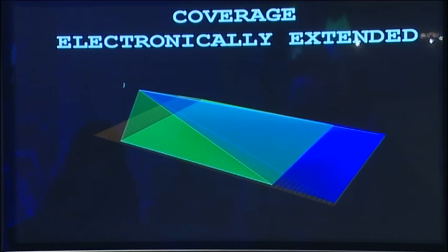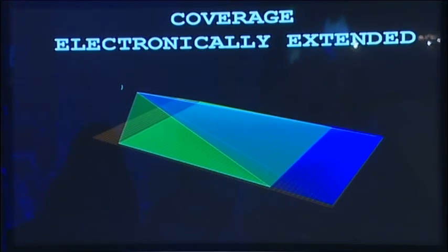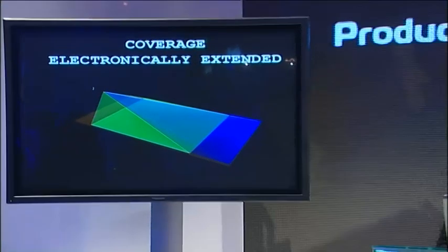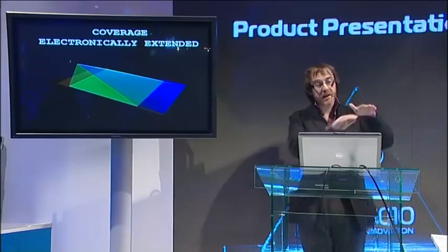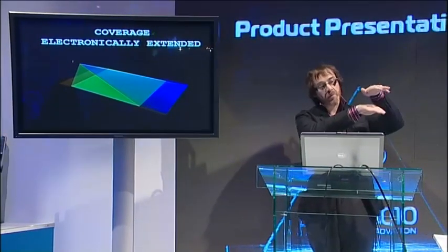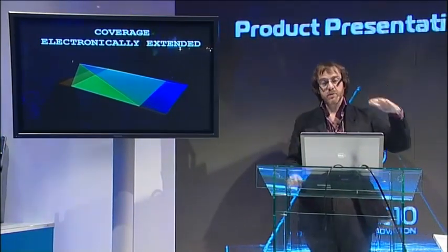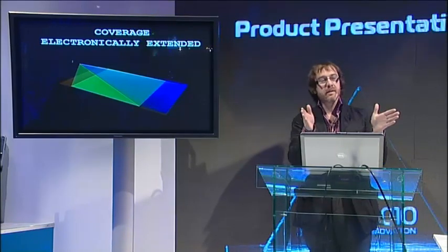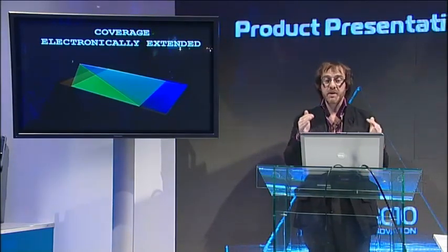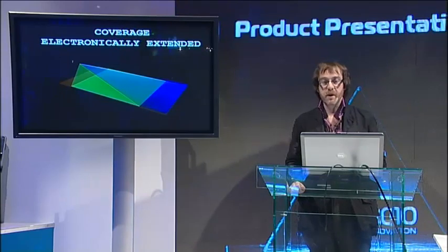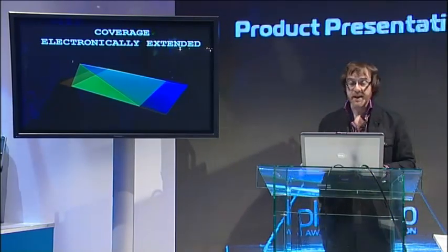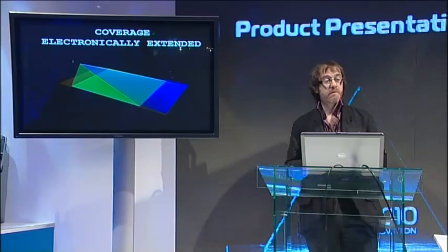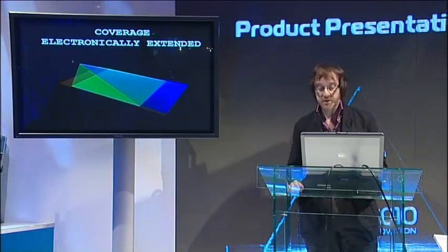You can also adjust coverage close to the stage as well as far away from it. And perhaps even more impressively, if you've got a very difficult acoustic surface in a venue, like a balcony, you can actually notch out the coverage to miss the balcony front. Typically we can broadband turn the level down by about 12 dB or 15 dB, which is a really, really useful reduction in reflection from these difficult surfaces. And again, it's all just done with DSP. There's no physical alteration of the array necessary to do that.